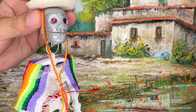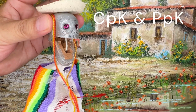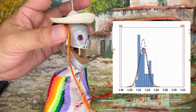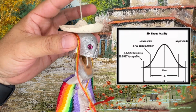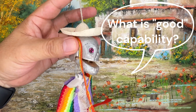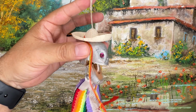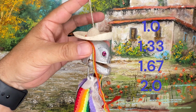And here are my final thoughts. Capability indexes such as CpK and PpK are great tools to analyze the performance of a process. You can easily determine if the process data is centered or shifted to one side. You can also easily determine the spread and the distribution of your data. But what is a good capability number? Well, that depends on your manufacturing or customer specifications. The most common required indexes are a minimum of 1.0, 1.33, 1.67, and 2.